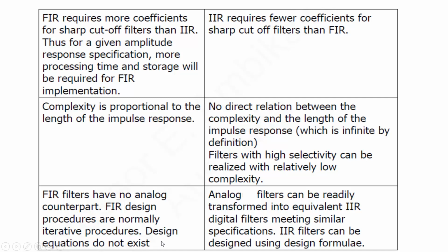So it requires a little effort to design the FIR filters, but of course they are stable and they have linear phase. Whereas the analog filters can be readily transformed into equivalent IIR digital filters meeting similar specifications. IIR filters can be designed using design formulas which already exist. We have to just make the transformation and we can get the desired response. But in this lecture, we will look at the design of IIR filters, one of the techniques of design of IIR filters, the impulse invariant technique.